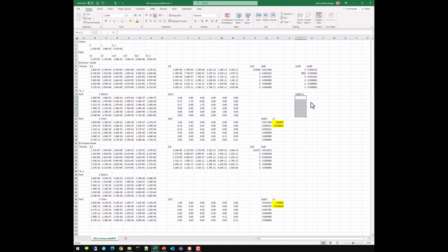And that's nothing more than the multiplication of my amplification matrix times my homogenized strains. And you'll see here that, kind of unlike the fiber, where I have 5,500 microstrain in homogenized, I have 9,500 microstrain in the matrix. So there's our factor of 2, give or take. You can see these numbers are on the order of 2 on the diagonal. So that's why the strain in the matrix is about twice as large.